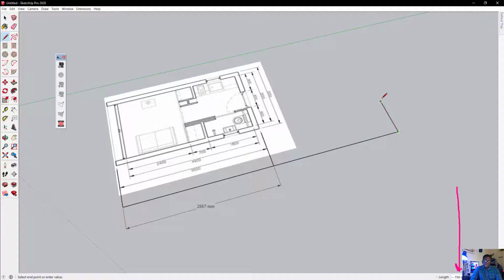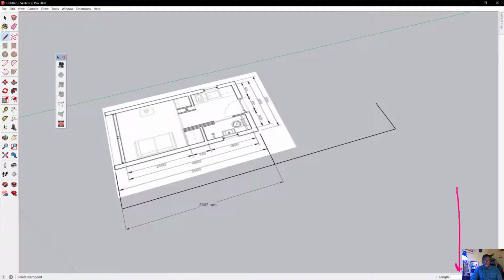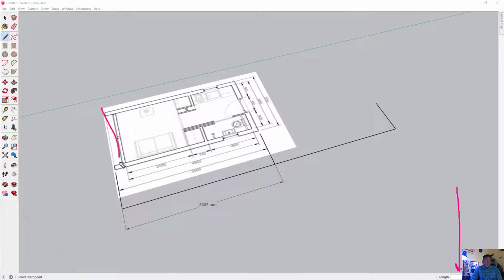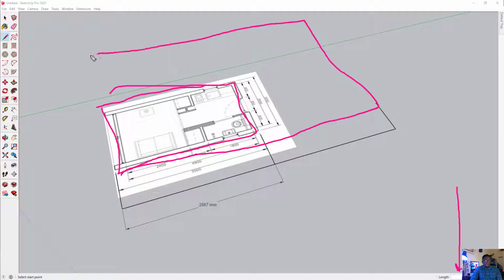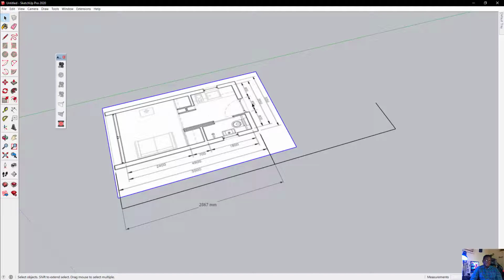So obviously my entire drawing that's about this needs to be rescaled, and possibly will be something like about that. So I need to now rescale this drawing here by upsizing it. Now, in order to do that, we're going to use this quick and easy trick. We're going to select that base there. We're going to go to the scale tool,